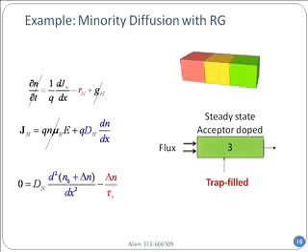So I put the second equation in the first one, and you can see that that will give me these two terms. The minority carrier recombination, delta n divided by tau n, right? That you remember. Now remember the various approximations we did, that applies in various cases. Had it been high injection, what would have been this value? Delta n divided by tau sub n plus tau sub p.